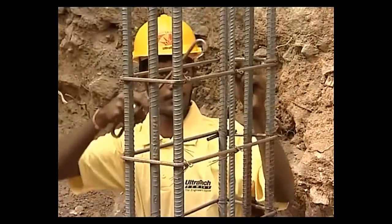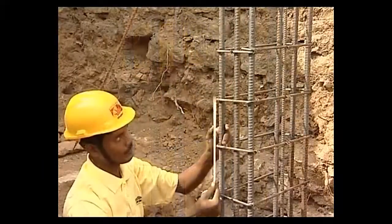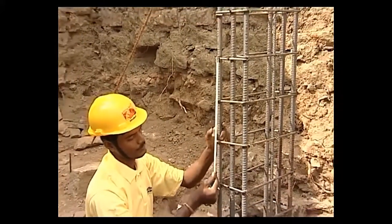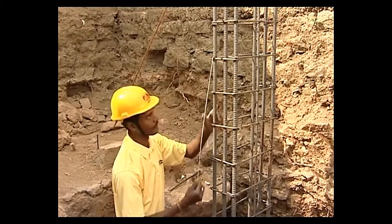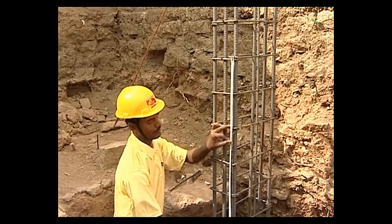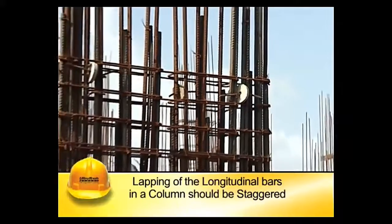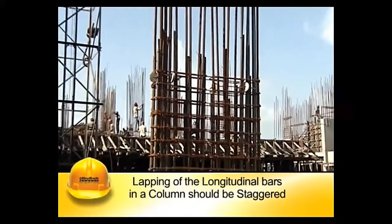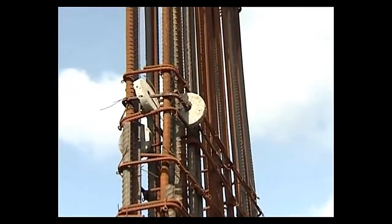The diameter and spacing of the lateral tie bars, generally called as rings, shall be as per the drawing and shall be checked by a professional engineer. Please note that it is advisable to have rings at closer spacing where vertical rods are lapped. The lapping of the longitudinal bars in a column should be staggered and not more than 50% of the bars shall be lapped at any location.